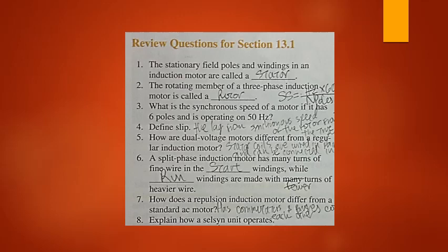Again, the definition of slip is the lag of the rotor from the synchronous speed of the stator field. Number 5, how are dual voltage motors different from a regular induction motor? The difference is that stator coils are wired in pairs and can be connected in series or in parallel.